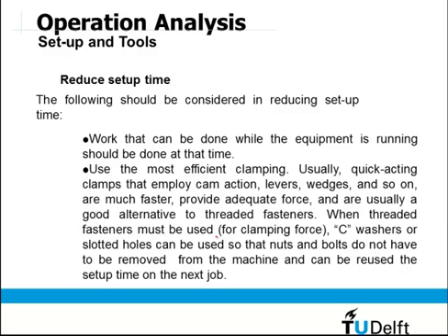Reduce setup time. The following should be considered in reducing setup time. How can we reduce the setup time, which is the time for preparing the operations or the machine? Work that can be done while the equipment is running should be done at that time. Some machines can be running while we do the setups, whether tools, jigs or fixtures; the machine can work while we prepare for this work.